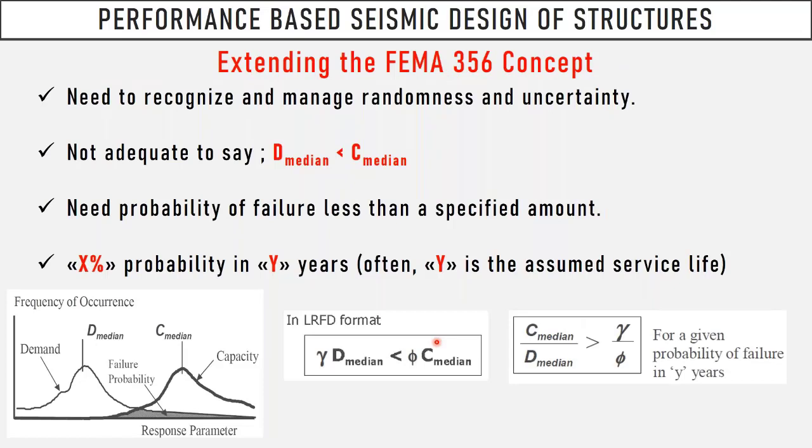And you extend it with the so-called FEMA 356 concept. Up to performance-based design approach, engineers just focused on what is your demand, what is your capacity, and if your capacity is greater than the demand, you are safe. But again, one thing is missing. The demand that you are talking about is the median, and the capacity you are talking about is the median also.